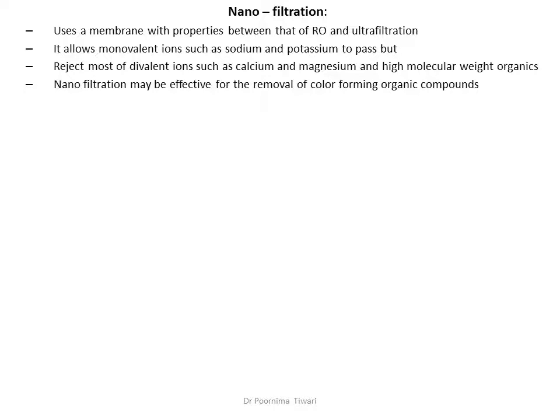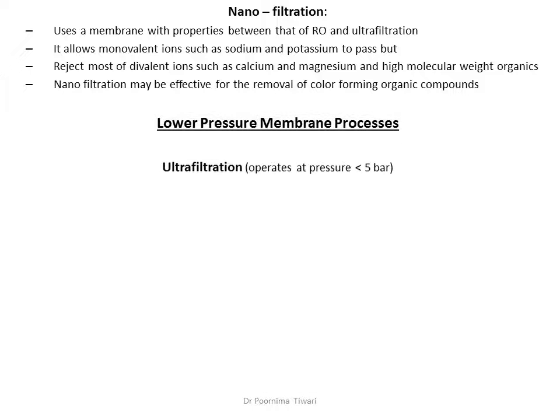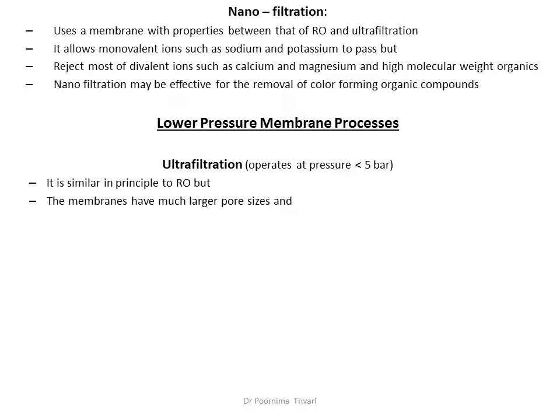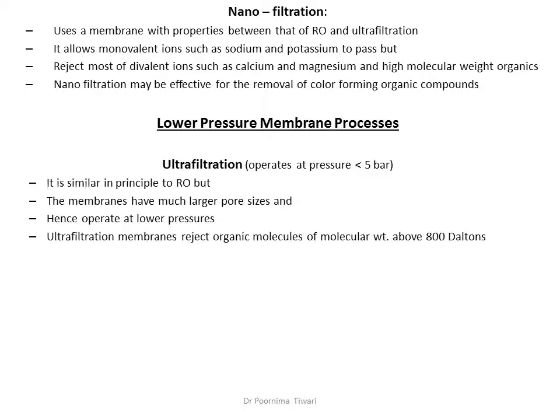Then lower pressure membrane processes. Ultrafiltration. It has large pores, so it can operate at low pressure. The principle is similar to RO, but the membranes have much larger pores and hence they can operate at lower pressure. Ultrafiltration membranes reject organic molecules.